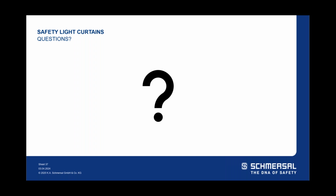In your light curtain designs, is the control reliability such that it meets guarding requirements of OSHA? Dave, I don't know if you know how to answer OSHA versus ISO. Ultimately, OSHA doesn't have specific regulations. It relies on consensus standards. At the very beginning, Craig, you mentioned several of the standards, the ISO 13849, which covers the design of control structures, the performance levels, and the safety integrity levels. So yes, our light curtains are designed to meet performance levels and safety integrity levels. To answer the question, it's yes. Thanks, David.